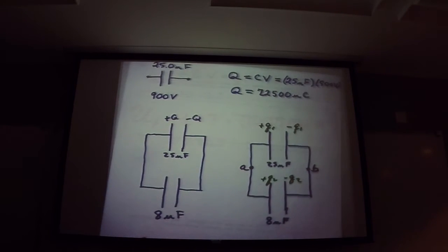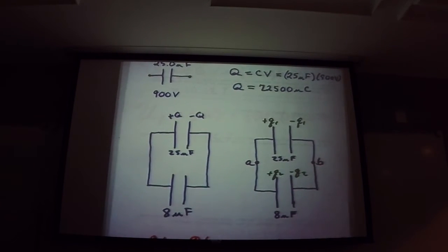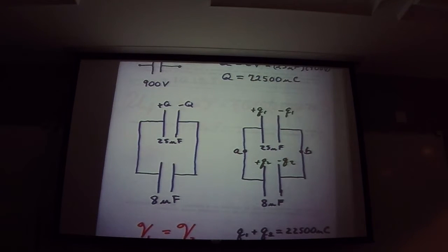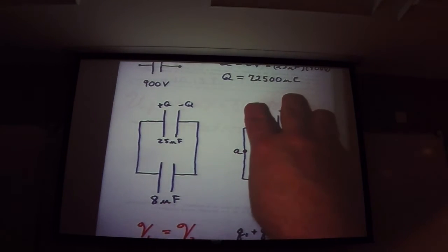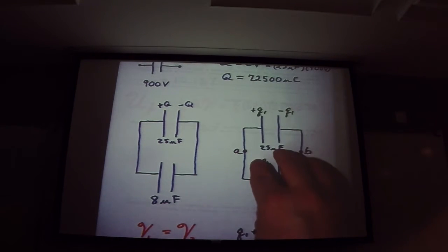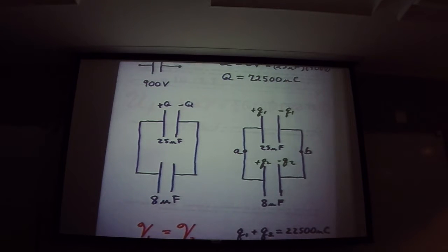Question? Yes. So if you add another capacitor to that, the voltage would drop more, but the charge would stay the same? The total charge on all of it would stay the same, yes. So in other words, what I did with the last problem was I treated this like an equivalent capacitor, which was the easiest way to do it. I could calculate each individual thing, but then I would just end up adding them up, and it would be the same thing anyway.